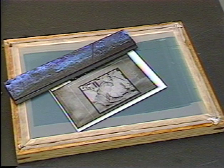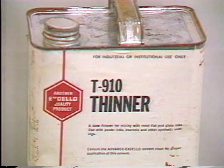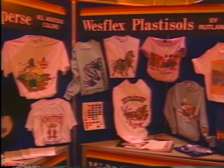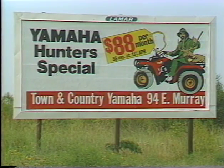Stencils for the process may be hand-cut or produced using photographic techniques. The type of stencil selected depends upon the solvents contained in the printing ink and other requirements for the job. Screen printing is used to print a variety of products, from textiles to bricks, and from circuit boards to containers and billboards.